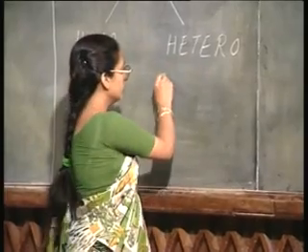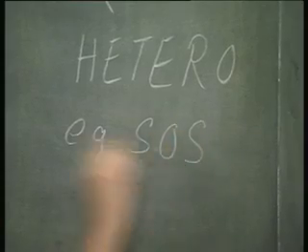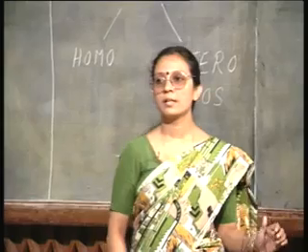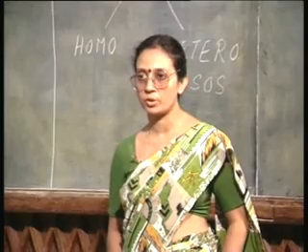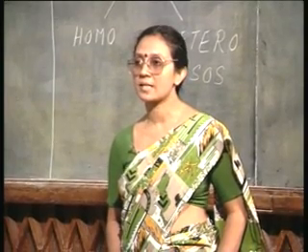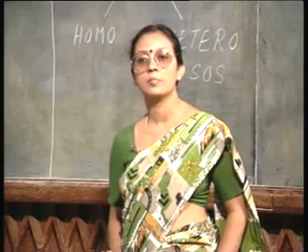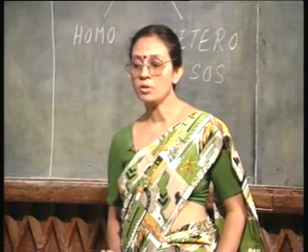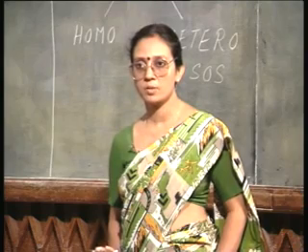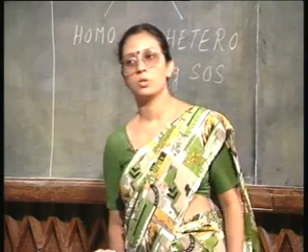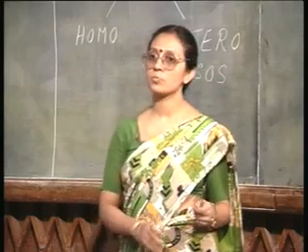Sapphire is actually nothing but aluminum oxide, Al2O3. It has a hexagonal lattice pattern, and silicon, as you know, has a diamond lattice structure. So, two dissimilar materials, silicon and sapphire, we want to grow one on top of the other. So, heteroepitaxy is necessarily much more complicated.